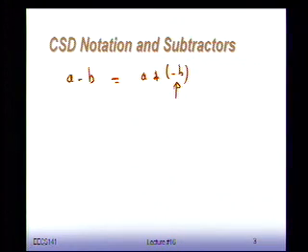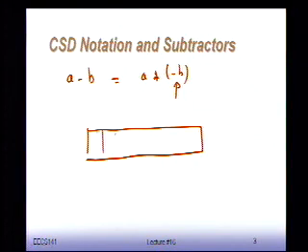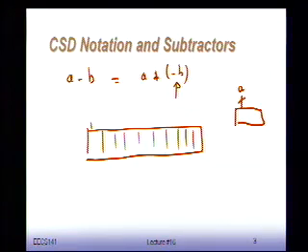Okay? So it turns out I can do this very easily with a full adder. I have my full adder, 8 bits in, A and B. So I have 8 segments here. Let me just write it like this. You have your full adder block, and one of the inputs is A, and that's 8 bits. So that's the add. Okay? If we want to do a subtraction, what we should do is add minus B, and minus B is B with all the bits flipped. So what I can do is take the B input and add an inverter on every bit. Adding that inverter for every bit does the bit flipping.